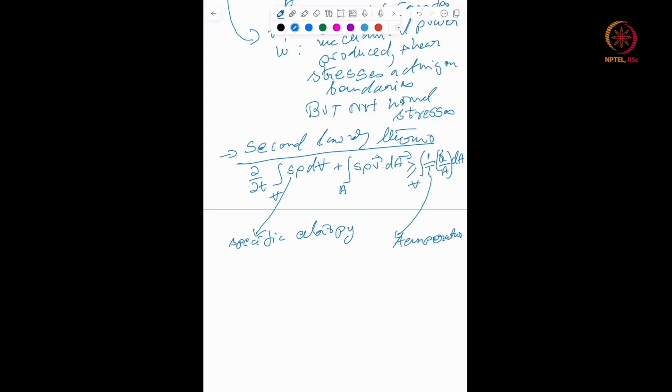Okay, all right. So by letting this control volume vanish towards a point, you convert these equations into differential forms, which you will see what they are. Okay, and of course there are other conditions, like for example, if you have a solid boundary, like a wall, then you have the no penetration and no slip.